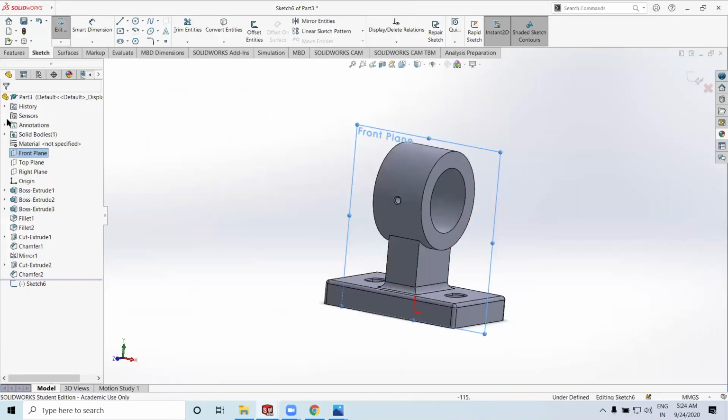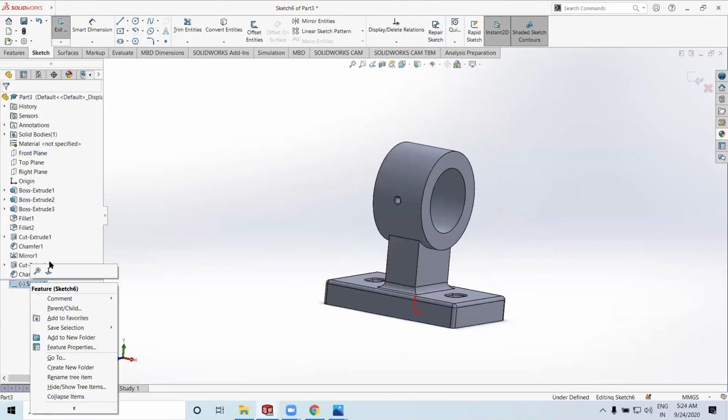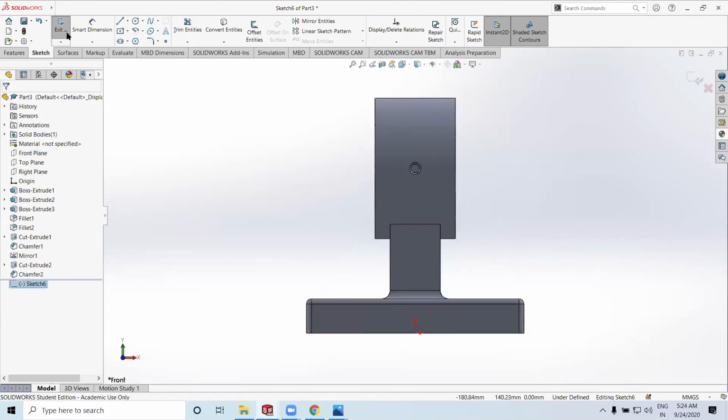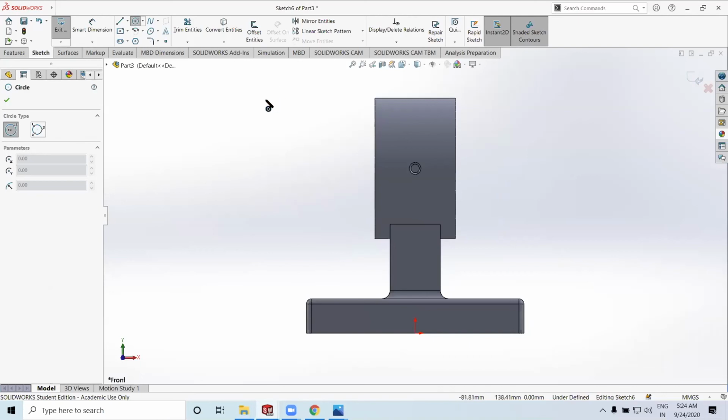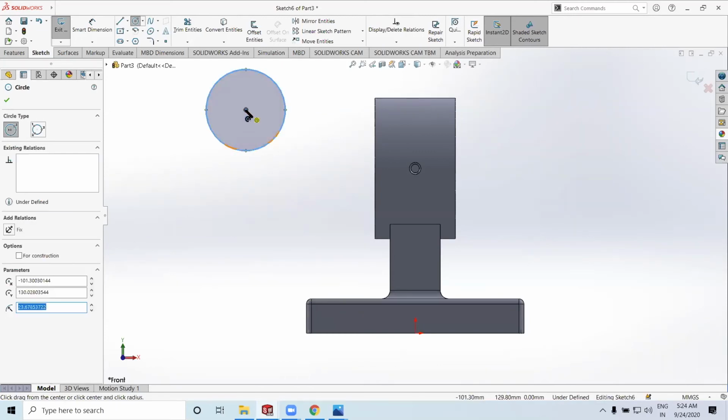So we do that. Just use the normal to icon and select the circular face. We don't draw on this part, we draw on the side for now. Draw two circles of any random dimension.